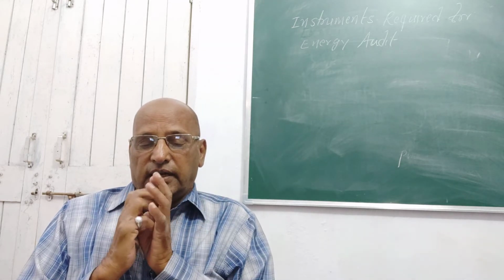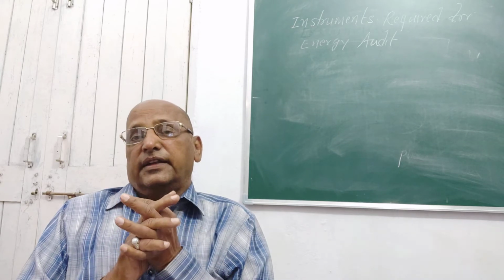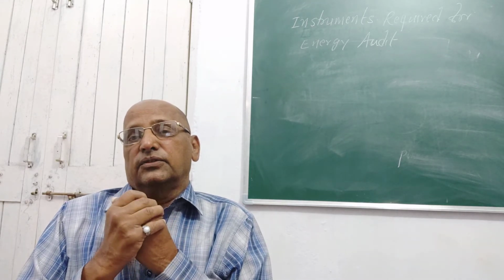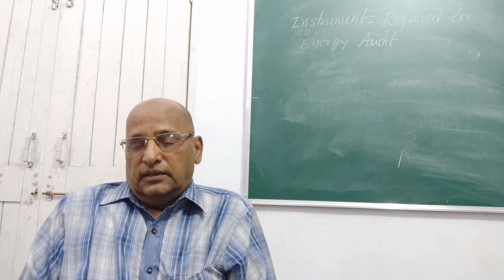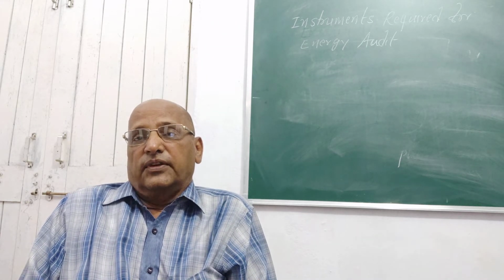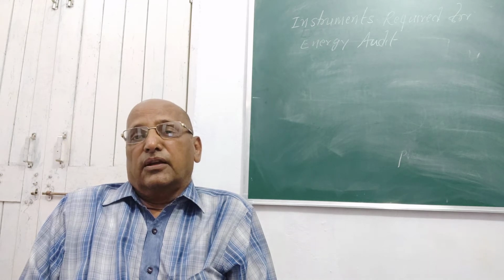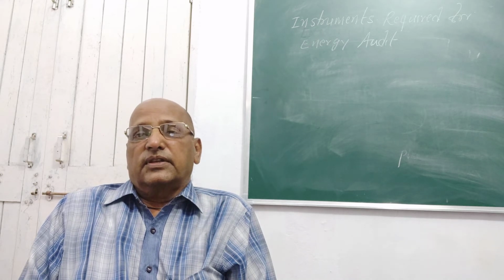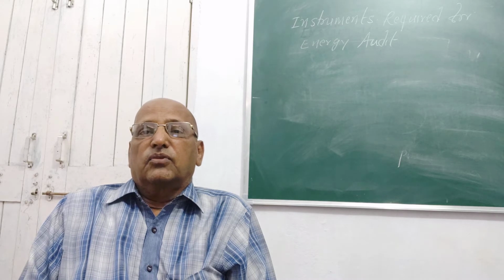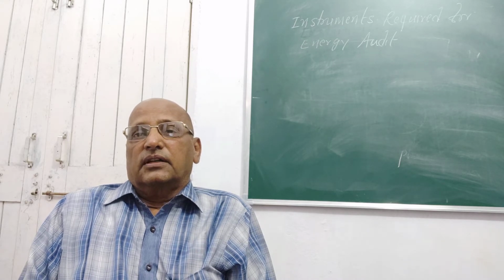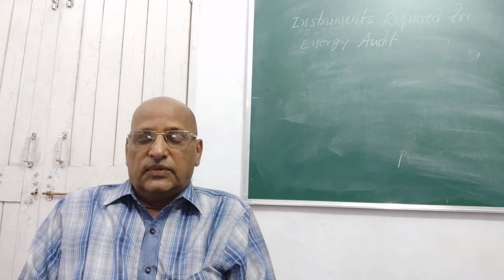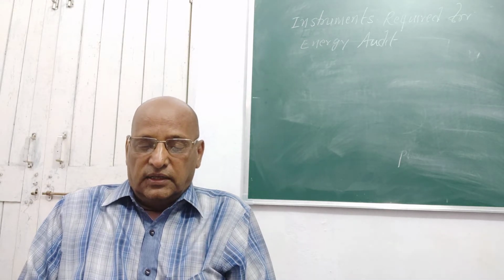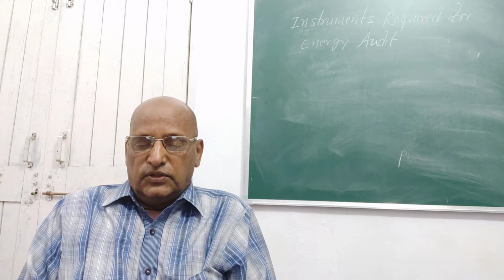Then we require a lux meter for lighting arrangement. Definitely, according to the standard, there are some values of light energy which are required on the surface, and according to the requirement of the surface, whether the same quantity of energy is being emitted from the source or not. For measurement of this we have to use the lux meter. This instrument measures the illumination level.